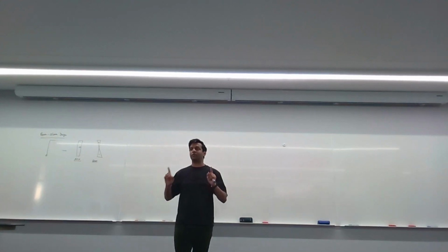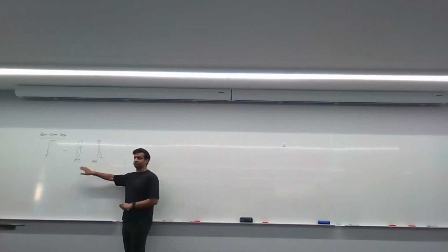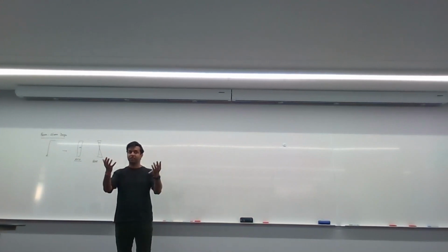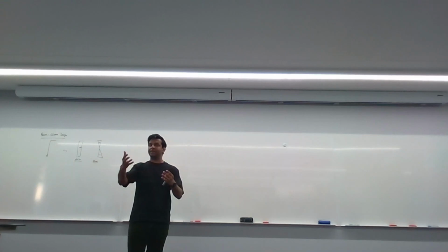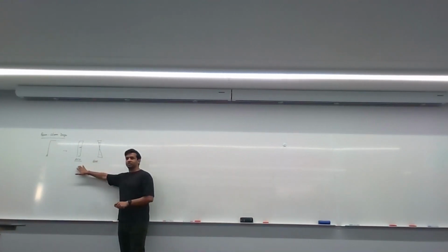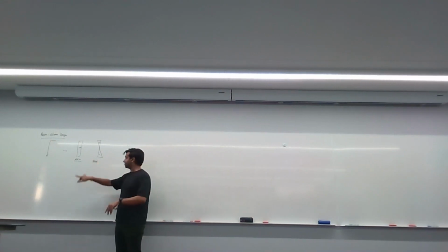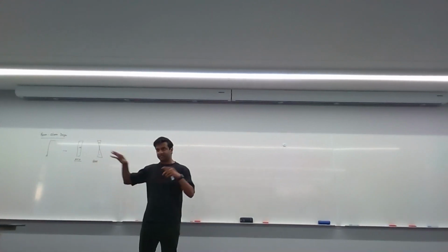At the end of the day, remember what you need before you start your step-by-step is your axial force diagram for your column, and you need the bending moment diagram. So what makes it a beam column? Remember, a beam column is a column. But the reason we're adding the word beam in there is because it's also bending. So apart from the axial force diagram, we also have the bending moment diagram. Your first step is to identify these two. Once that's done, then we can start with the step-by-step.